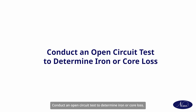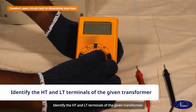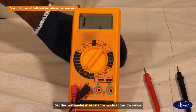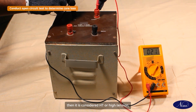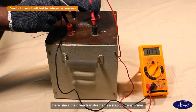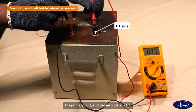Conduct an open circuit test to determine iron or core loss. Identify the HT and LT terminals of the given transformer. Set the multimeter in resistance mode at the low range and measure the resistance of the primary and secondary windings. If the resistance value is high, then it is considered HT or high tension, and the low resistance value is considered LT or low tension. Here, since the given transformer is a step-up transformer, the primary is LT and the secondary is HT.